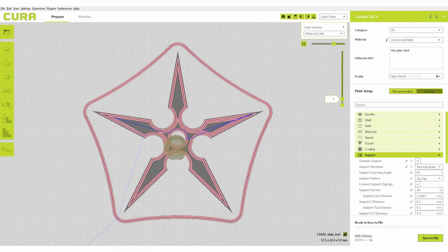A closer comparison of the reconstructed model to the printed object reveals that the printing process involves some distortion of its own. The original model is processed by a slicer before it can be printed, and the slicer makes a few modifications. One of these is to place the printing toolpath slightly inside of the object's outer perimeter.